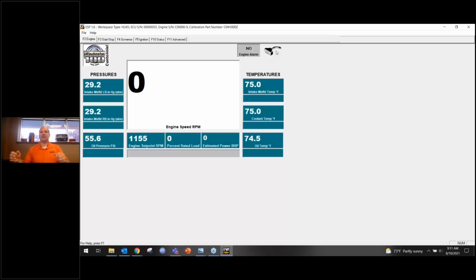Sometimes there's a little language difference between those two. So we've seen people who had cables and cords that worked, and all of a sudden they say, nope, it's not working anymore. Check out that converter. A lot of times there is a driver or software used to take that 9-pin connector, or 9 communication pieces plus the outside ground, and transfer that over to a USB, which has 4 pins plus the outside. So 10 pulses to 5 pulses, you need some software to figure out how to make that work.